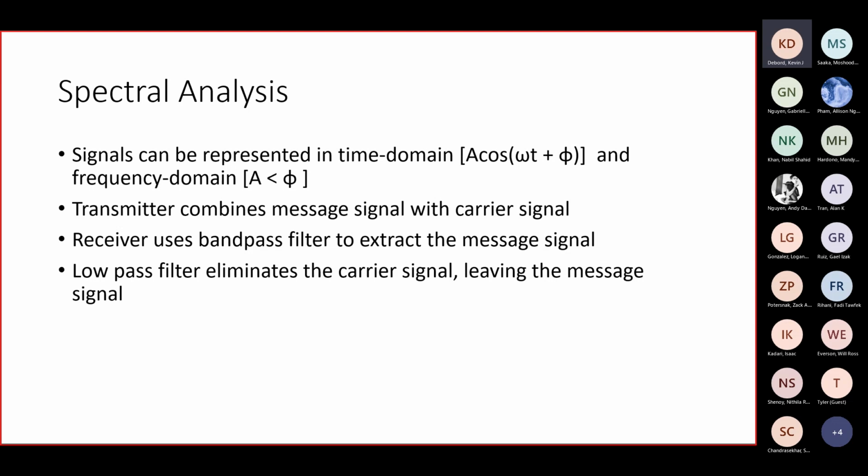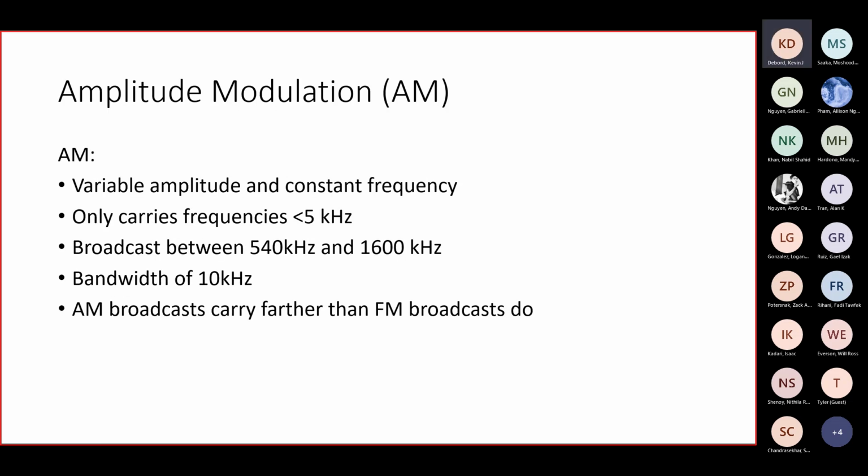So one thing you guys might have gotten wrong in your quizzes: what filters do we use? Are we all thinking about the same question? It's the filter used to grab that carrier signal and then filter it out, right? I believe it's a band pass and a low pass filter. So just try to remember that. It's both.